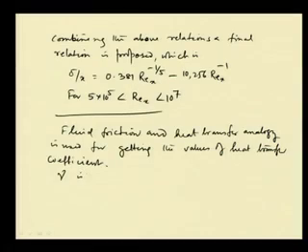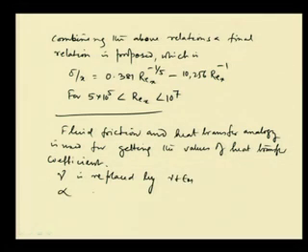What is being done is that momentum diffusivity is replaced by nu plus epsilon m, and alpha, thermal diffusivity, is replaced by alpha plus epsilon h. This is the molecular momentum diffusivity plus eddy momentum diffusivity, and this is the molecular thermal diffusivity, and epsilon h is the eddy thermal diffusivity. These are the diffusivity terms which are being used in case of turbulent flow analysis, that already we have discussed when we discussed the analogies.